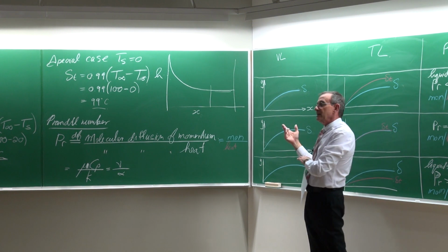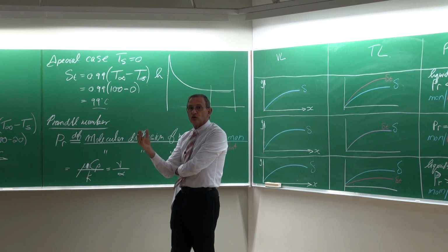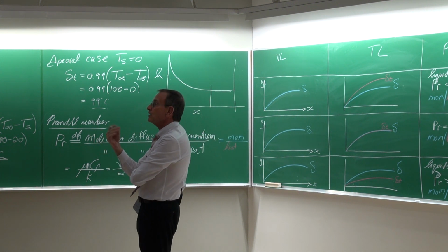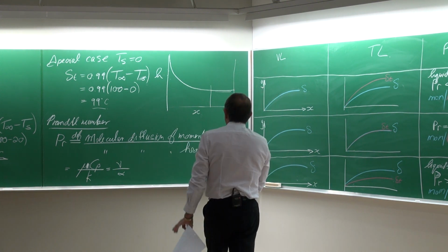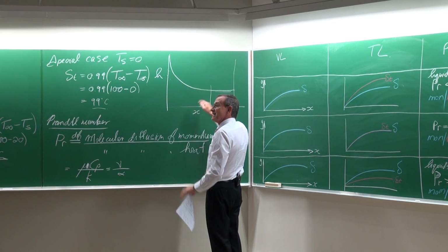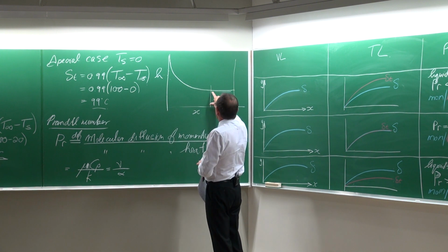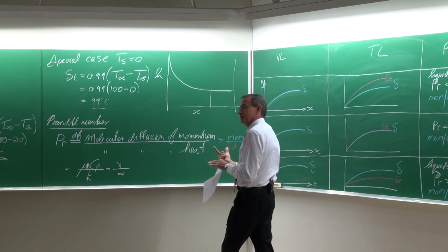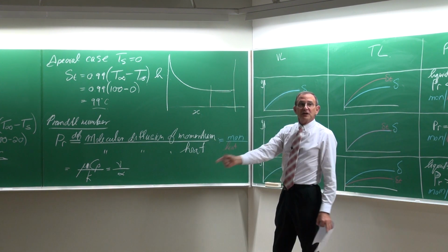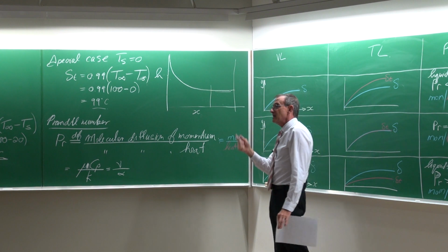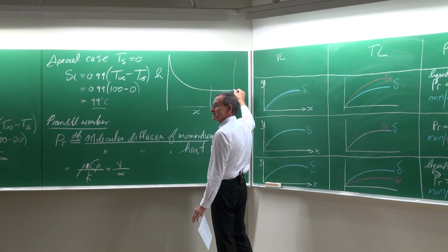In terms of getting the heat transfer coefficients so that you can do your design, normally you need the heat transfer coefficients to determine how much area you require to transfer a certain amount of heat. So this shows us if the boundary layer is developing, then the heat transfer coefficients are much higher than when it is fully developed. If it's fully developed, then it stays constant. So many of the equations which are available in industry would typically have these values, which are the fully developed ones, which are the simpler ones.